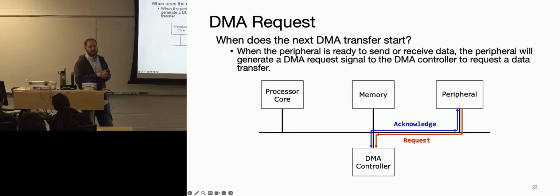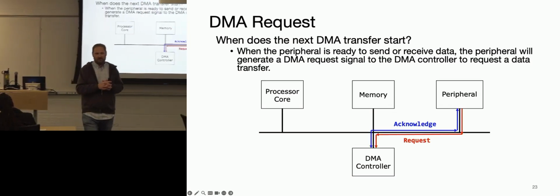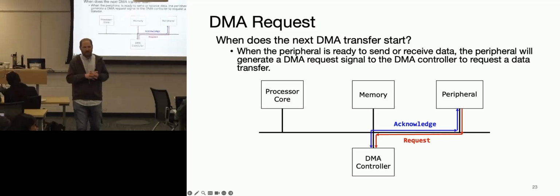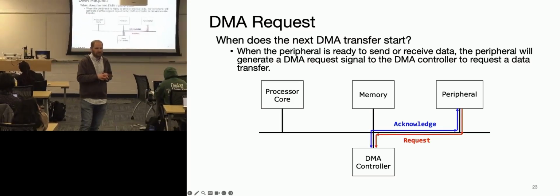I guess this is more of a practical question, but when configuring the DMA controller in STM32CubeIDE, how do you tell it where the circular buffer and ping pong buffers are? I imagine you'd have to allocate those in your main.c and then pass in a pointer or something. But you don't know that until after you auto-generate, or does it allocate the buffers for you? When you compile it, it'll allocate them. You just say this is the variable, right?